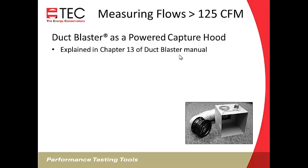You can use the Duct Blaster Fan as a powered capture hood, and that's explained in chapter 13 of the Duct Blaster manual. So that gives you some more details on how to fabricate that box, and you can use this for measuring supply readings also.